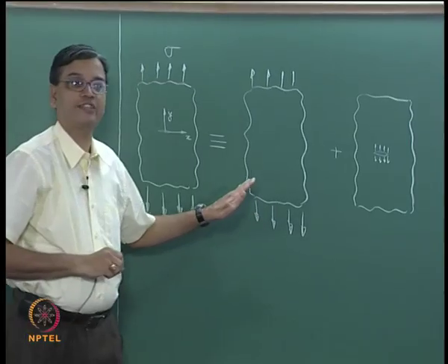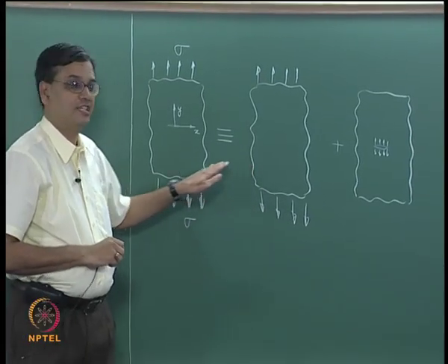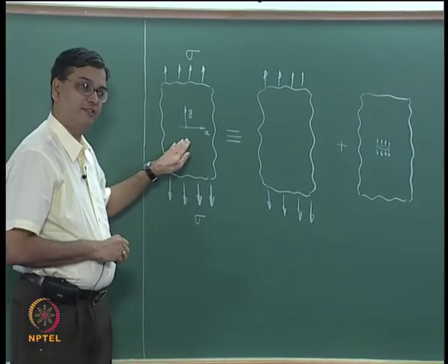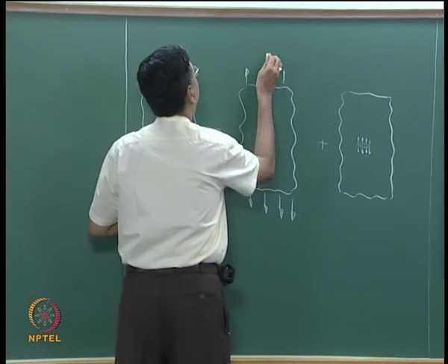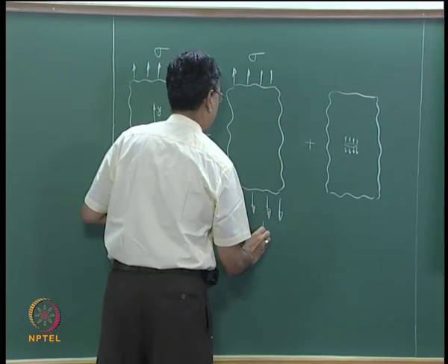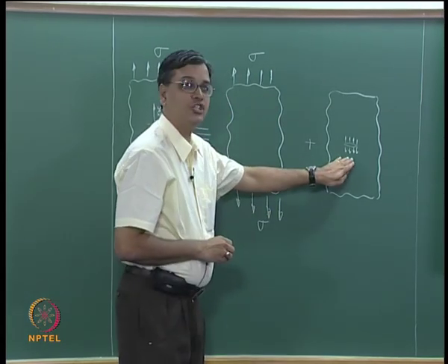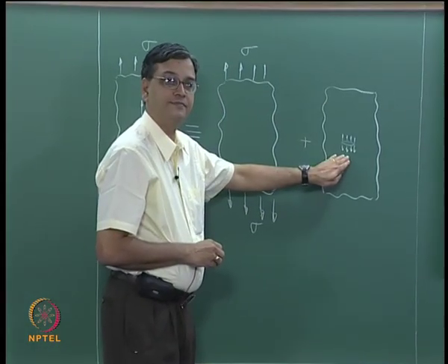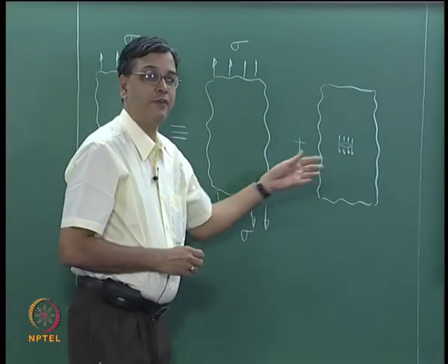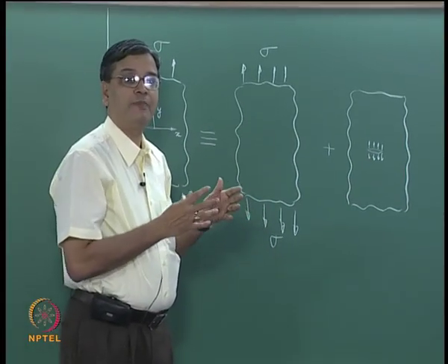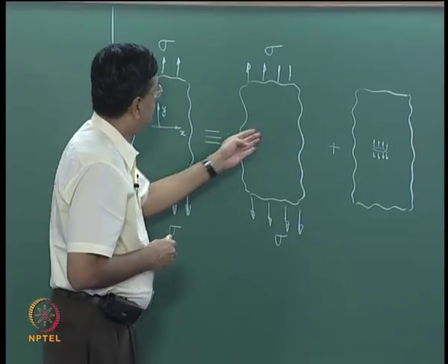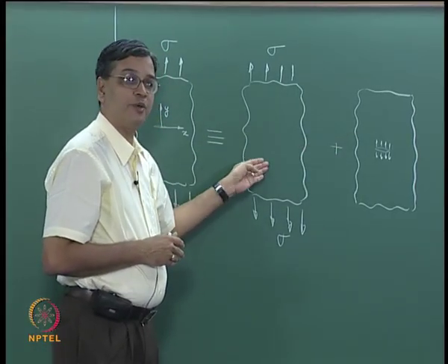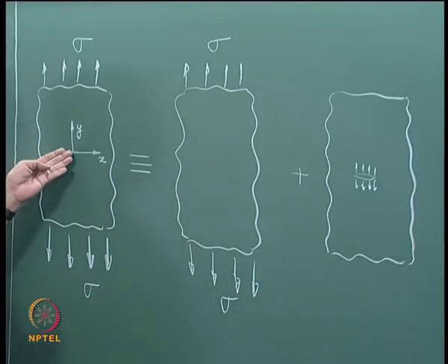Can you agree to this kind of an explanation? This is the problem that I have. This could be thought of as solution of this problem plus solution of a problem like this. And from our knowledge of developing stress intensity factor, whatever the stress intensity factor I get out of this problem should be same as what I get in this problem.